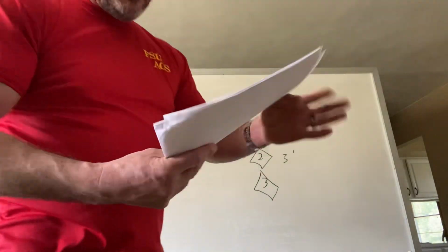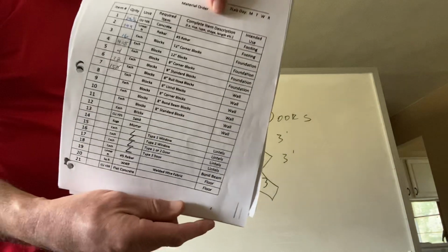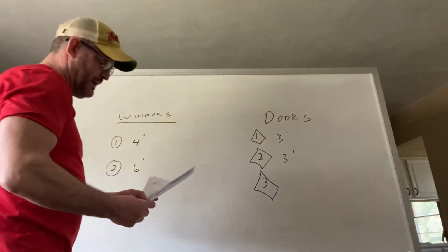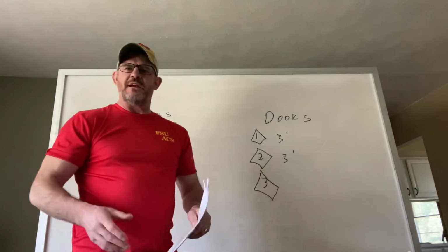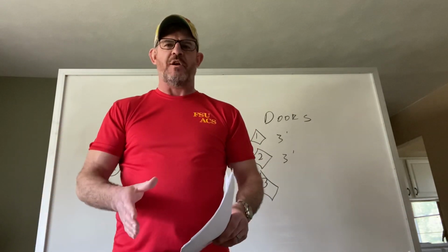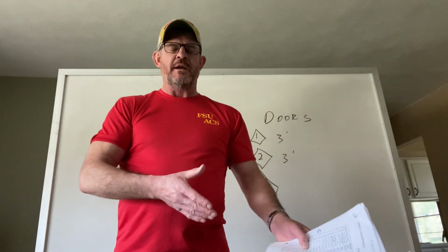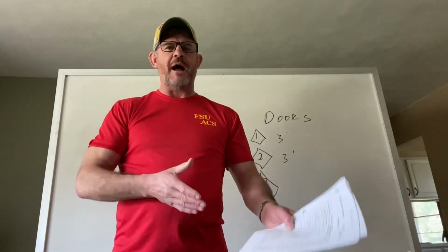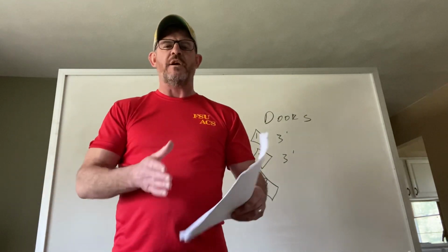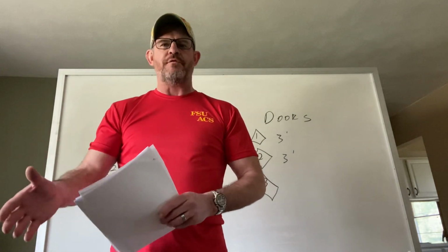And we see that in a couple more items, we have to determine the number of bond beam block. All right, what is a bond beam? A bond beam is the exact same block as a lintel. It's the same piece of material, but it's not used to carry weight over an opening. The difference between a lintel and a bond beam: while they're both the same block, the lintel carries weight over an opening. A bond beam is a part of our overall reinforcing.